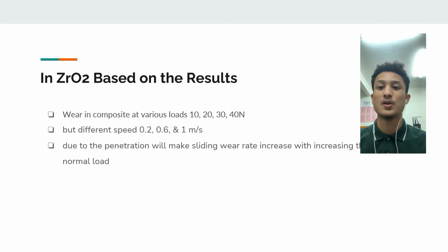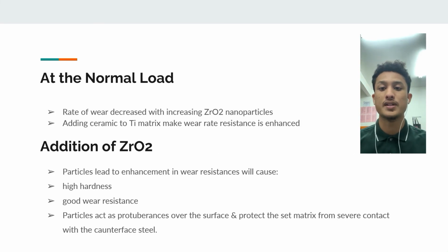At the normal load, firstly, the wear rate decreases with increasing zirconium dioxide nanoparticles. Finally, adding ceramic to the titanium matrix made the wear rate resistant and increased hardness.